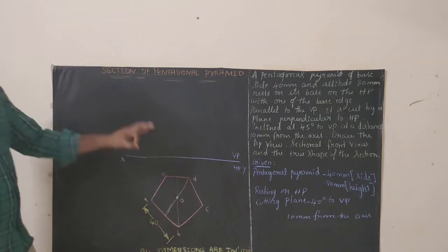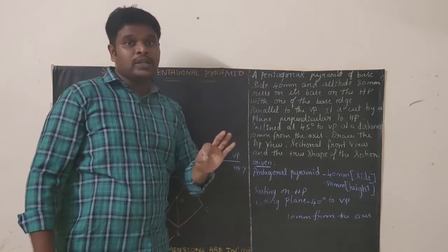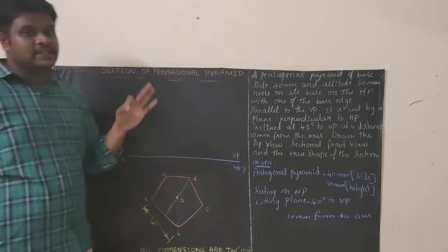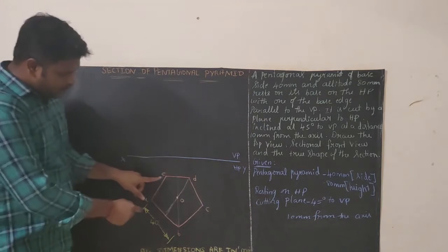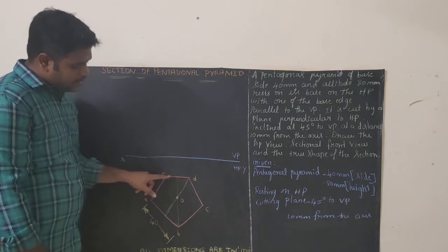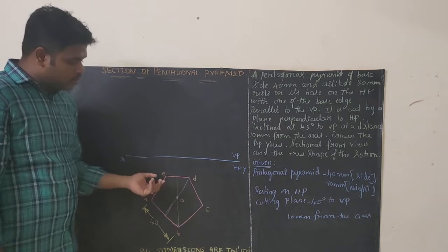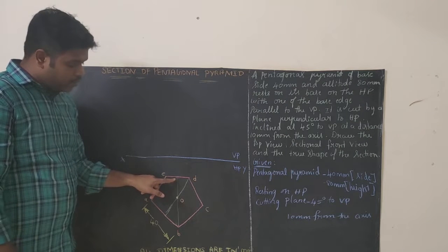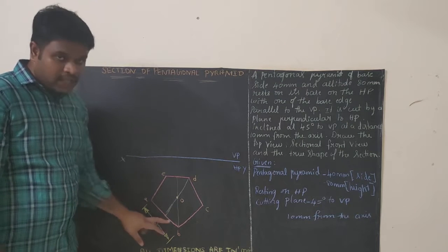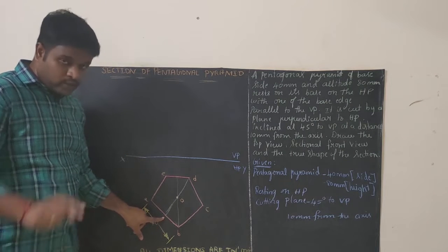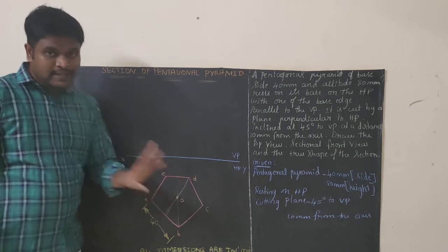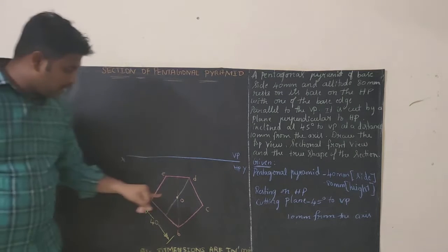Next thing is, whenever you are working with a pyramid, you have to give preference to slant edges. So remember this point in your mind. Slant edge is very, very important. See here, if this is the base, opposite to a corner, just bisect ED, whatever may be the distance. So 20 will be there, right? Just mark a point at 20 and join it with B. And here AB, just measure AB, 40 will be there, bisect this line, 20. Just join it with the opposite corner D. So these two lines intersect at one point, right? That point is called O.